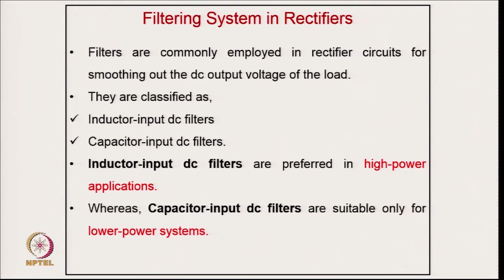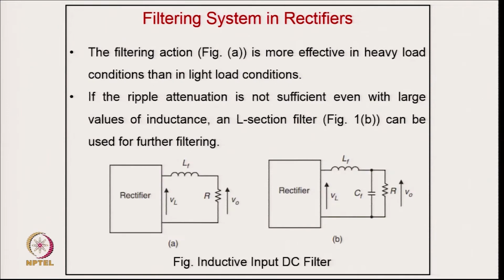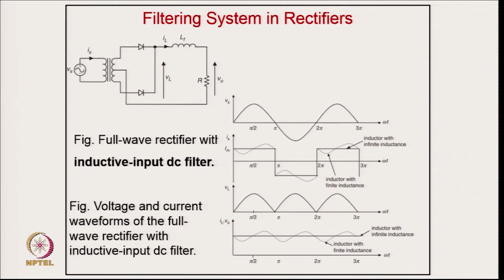So, you are using different kinds of filters, which we have shown in the circuit, and performance changes with the filters. If you are using an inductive filter at the input supply, the current will typically be flat, and the crest factor will be less than for a sine wave. If you are using an LC filter, it is in between, but if you are using only a capacitive filter, the crest factor goes very high, as you draw a peaky current.